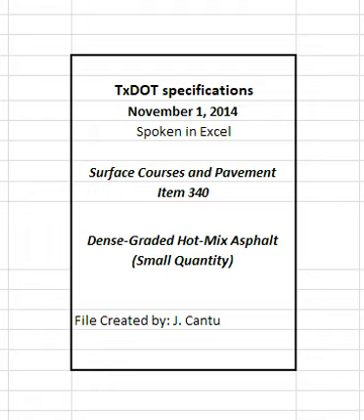Perform other tests on RAP and RAS when shown on the plans. Asphalt binder from RAP and RAS is designated as recycled asphalt binder. Calculate and ensure that the ratio of the recycled asphalt binder to total binder does not exceed the percentages shown in Table 5 during mixture design and HMA production when RAP or RAS is used. Use a separate cold feed bin for each stockpile of RAP and RAS during HMA production.